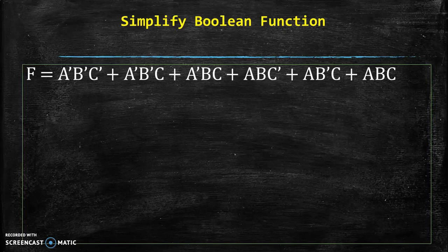In all the product terms we have literals of all the variables A, B, C, and that is why it is standard or canonical SOP form. If it is not in standard or canonical form, then first we have to prepare a standard SOP form and then find the minterms. But in the given example, it is in standard SOP form, so we proceed further.